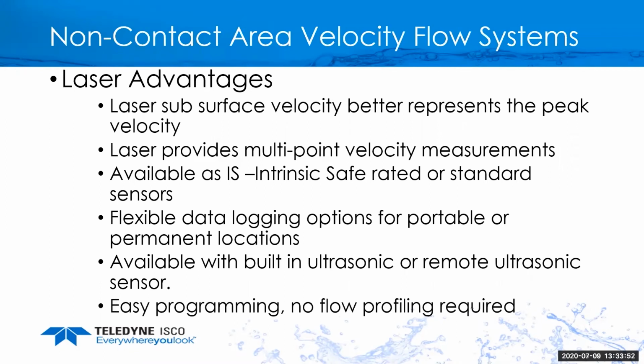Easy programming. We want to make these things as easy as possible. And most of them are, you can program in the pipe size, you set the level, and away you go and you're done. But you really don't want to have to go in and profile. That's one thing where I know a lot of people do that. That's kind of old school stuff, and that's been done for years. Doesn't hurt. Not a bad idea, but that technology's been out since probably the late 80s. So electromagnetic point velocity is a good comfort reading, and it'll tell you, yeah, you're pretty close. But I always rely on the meter to give me the most accurate reading.